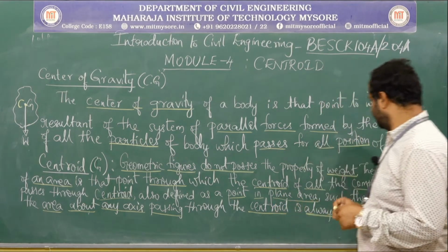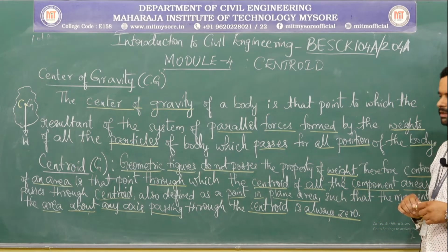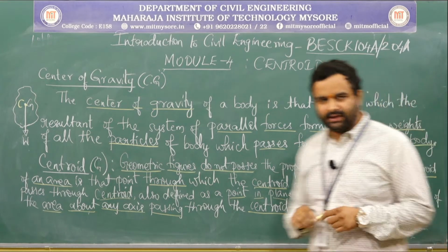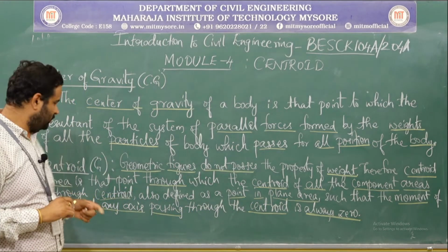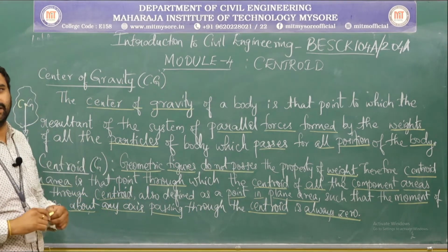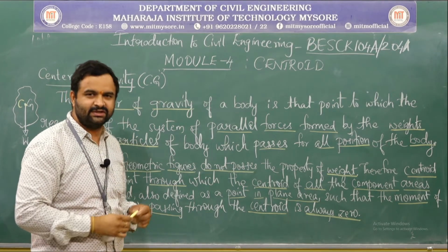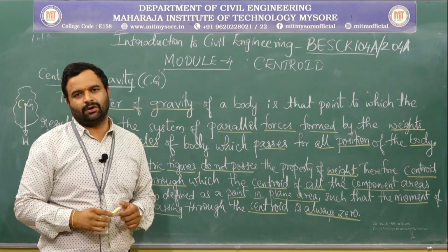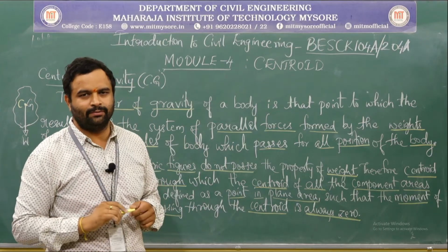The centroid is defined as a point in a plane area such that the moment of the area, see, here we are not talking about the moment of a force, it is the moment of the area about any axis passing through the centroid, is always 0.